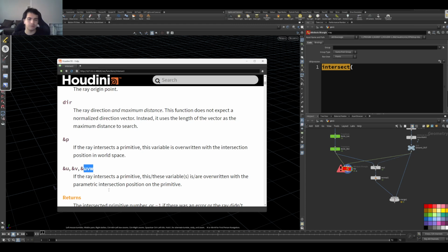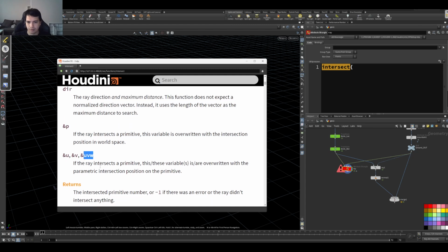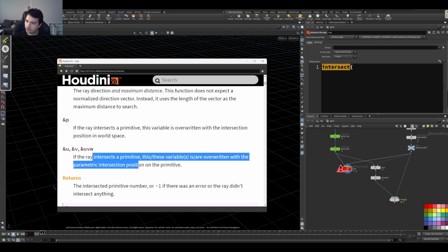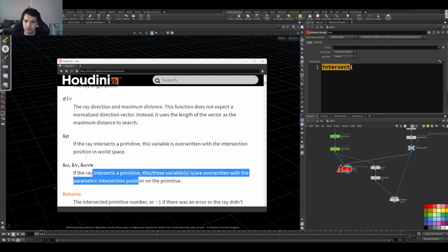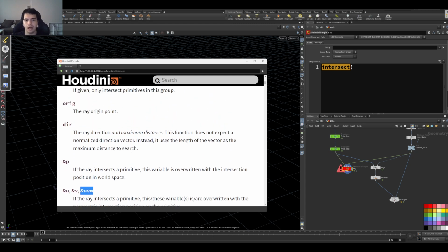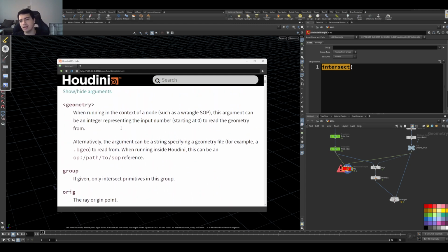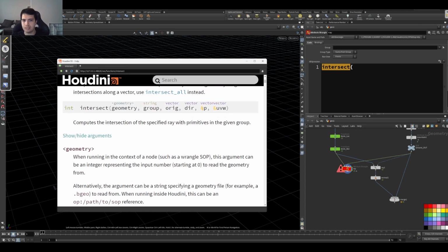In Houdini we have UVs of course, but also prim UVs, procedural UVs that specify a very specific position on a primitive through a vector. Just like the curveu attribute actually.